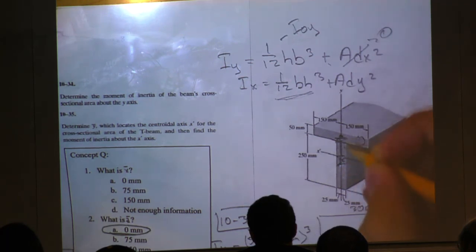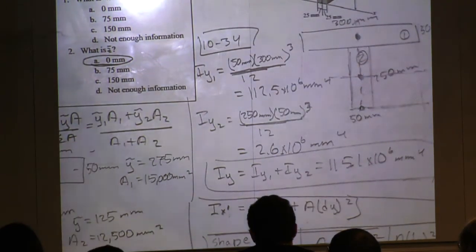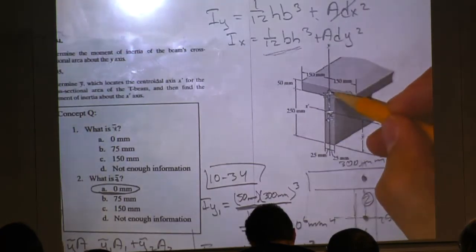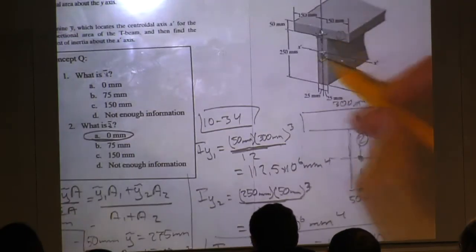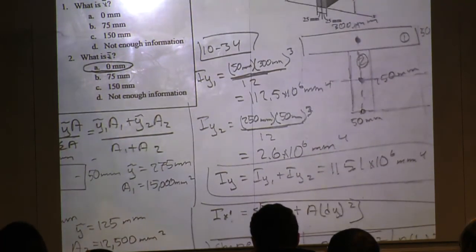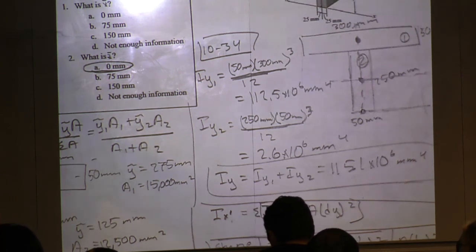These distances between the axis and the centroid. In this case, it's the y, because that's what's given in our equation. So I found these distances from here to here, because it's this centroid minus, right, so this centroid was 275, and I subtracted the y bar that we found, 206.82. And so I got, because I squared it, 4,624 square millimeters. I squared it because that's what we have to do in the equation, so I can make it easier. And then 67424 rather.